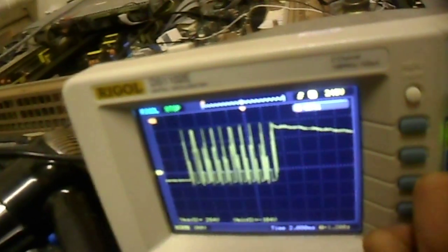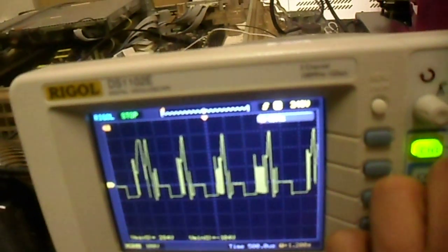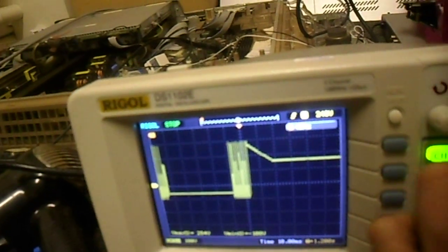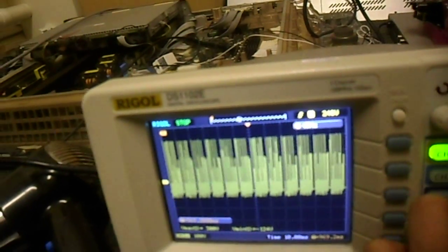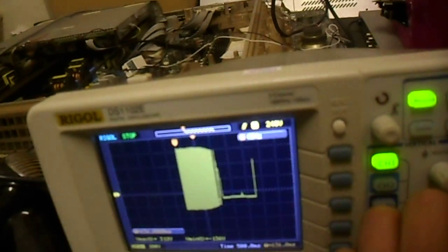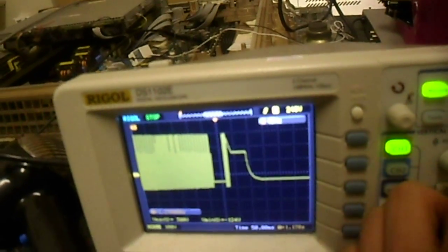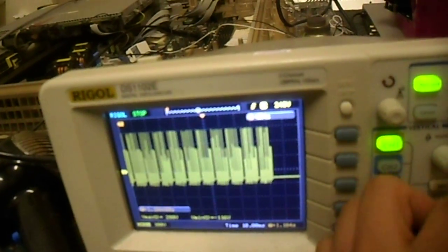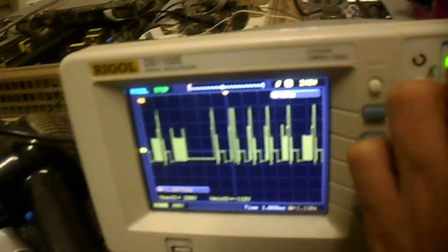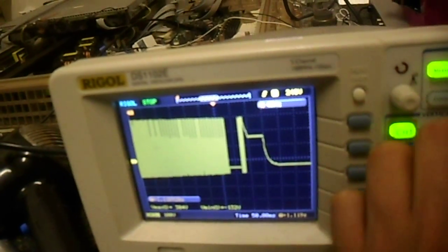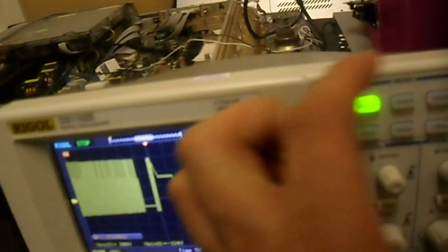Shut down. And so what we see, the shutdown process is obviously microprocessor controlled. Look at the fantastic resolution on this thing. So what we see here basically is the sustain voltage begins collapsing, and once you get below about 10 volts of the normal sustain voltage, you basically get no light emission from the plasma panel, or very little. You might get the occasional pixel, and so the current basically falls off very rapidly. And so generally, what dies first is not the sustain voltage, but the main board, because it loses power. All the other logic loses power before that.